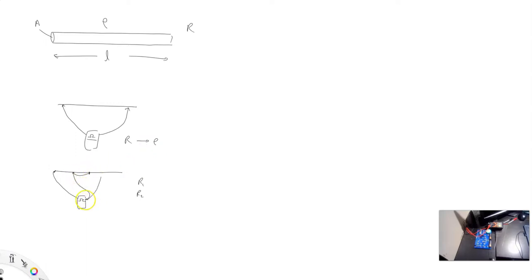I place the probe over here, so I have a different length, right? So L1, L2, that is from here to here, L3 from here to here. Like that, I can slide this probe along the length of the wire, take multiple resistance readings. That way I have multiple resistivity values. Probably I can take the average as the answer.